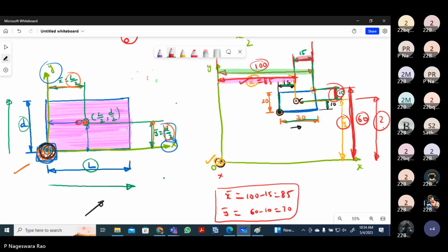We have to apply the formula as per standard shapes. Whatever the formula from the origin, then we have to measure the same centroid from the origin, and write the coordinates. If it is only one area, I write x bar, y bar. If there are several areas, say 3 areas, then we have to write x1, y1, x2, y2, x3, y3 like this. This procedure has to be applied. So now consider this rectangle.